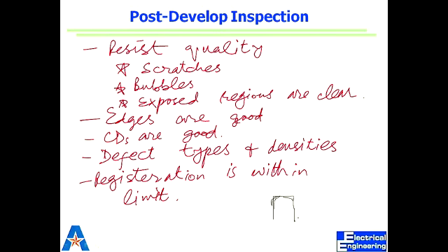Gate level mask is the most critical, where we have the smallest feature. There I'm really careful. But if I'm running contacts or interconnects, I'm more concerned about the integrity of the line and the length that it reaches. It would be a lot bigger in width, but I would be more concerned that the metal is not thin at any place, because that's going to result in failure. I'll be concerned about overhangs of metal. We'll see what overhang is on the next slide.